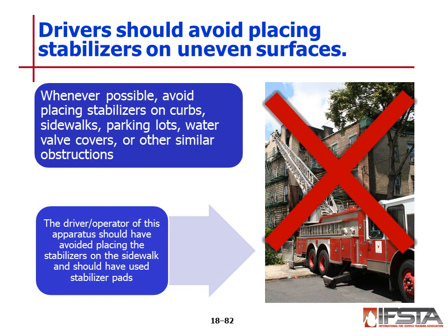Pre-incident planning will help identify areas that are safe and unsafe for apparatus placement. Err on the side of caution. The driver operator should always ensure that the object or ground surface upon which stabilizers are resting is solid and capable of supporting the necessary weight.